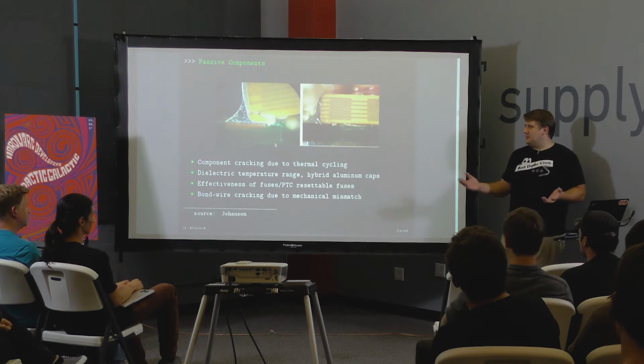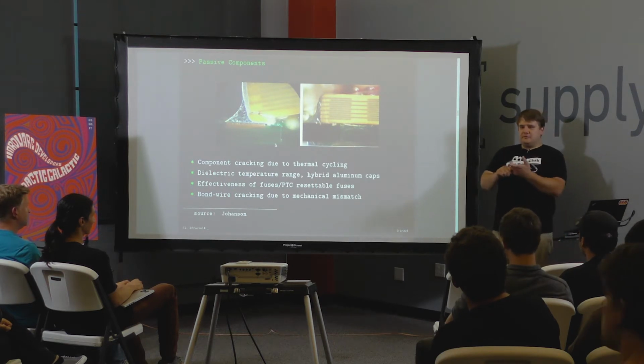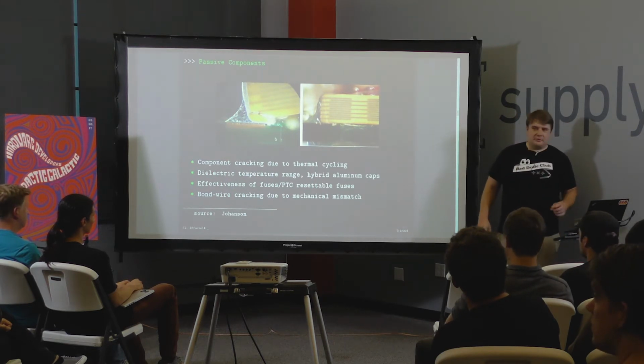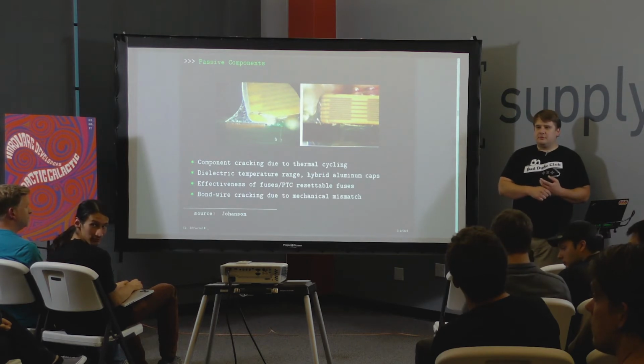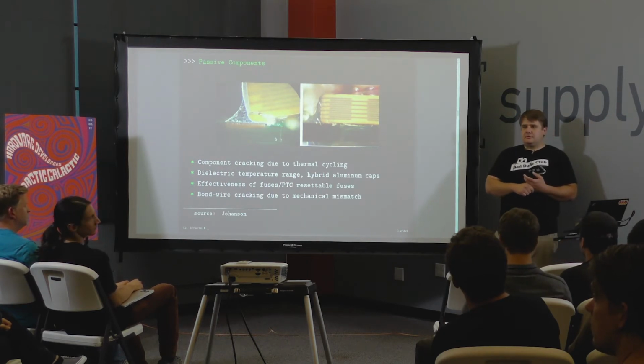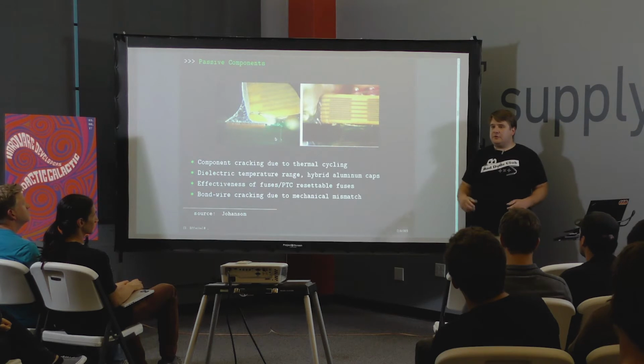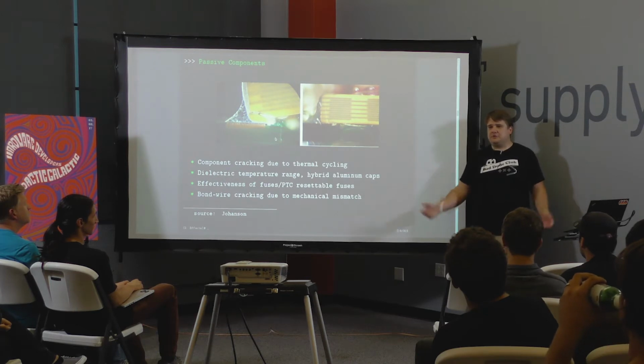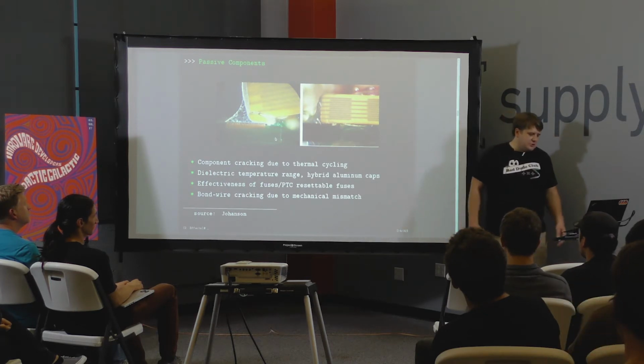So look at other ways, maybe active, of monitoring current. What about just using a different rating fuse, characterizing its behavior down to those temperatures? You could, but if you're testing on the ground, you have to look at the varying temperature ranges. For some stuff, it's fine. It depends on what you're trying to do.